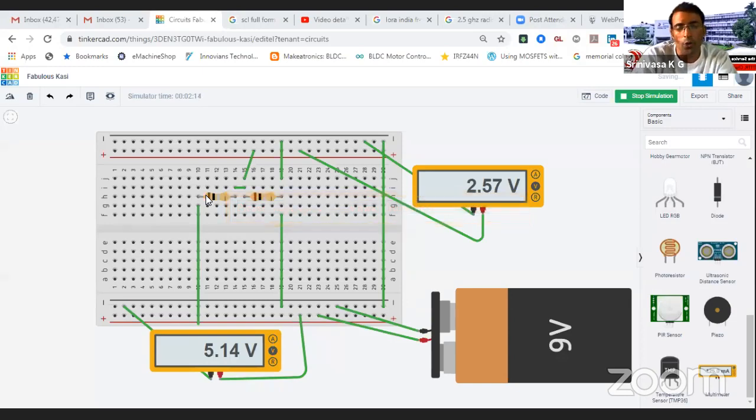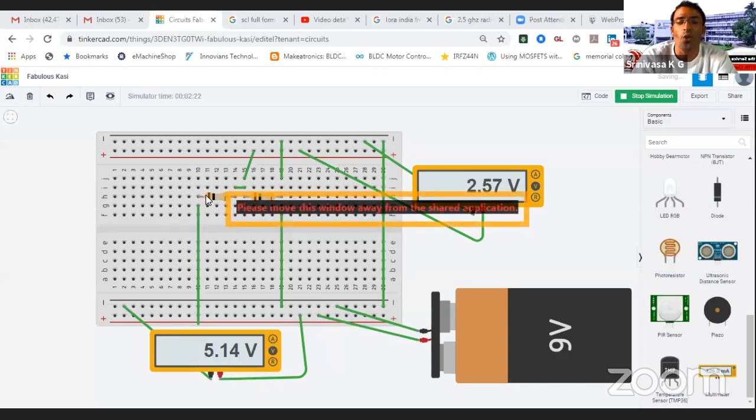Because if you connect a very low resistance value, then the battery consumption in your circuit will be higher and your circuit will not be optimum. And if you are using a very high amount of resistance, then you will not get proper voltage at the output and your circuit will not work efficiently. The sensitivity of your voltage divider will get reduced. So hope you got it.